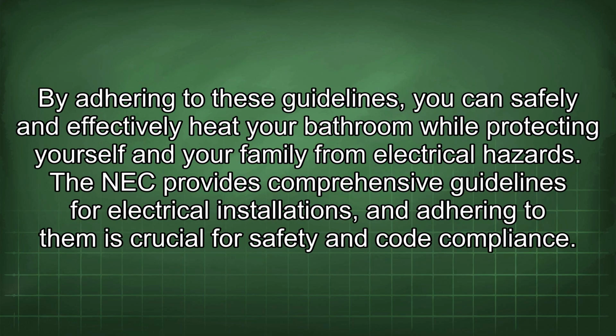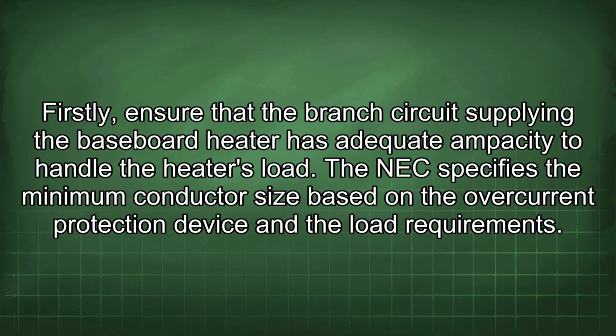By adhering to these guidelines, you can safely and effectively heat your bathroom while protecting yourself and your family from electrical hazards. The NEC provides comprehensive guidelines for electrical installations, and adhering to them is crucial for safety and code compliance. Firstly, ensure that the branch circuit supplying the baseboard heater has adequate ampacity to handle the heater's load. The NEC specifies the minimum conductor size based on the overcurrent protection device and the load requirements.